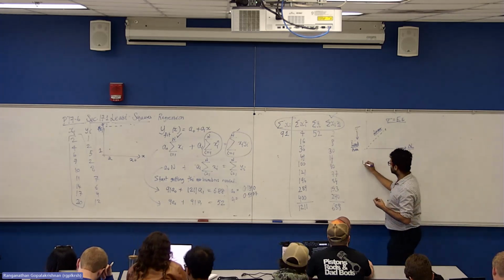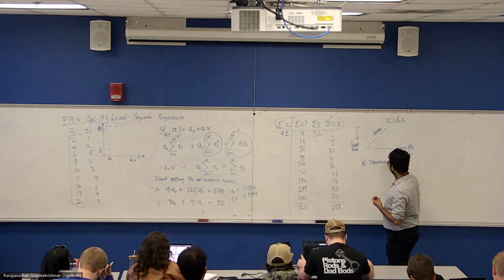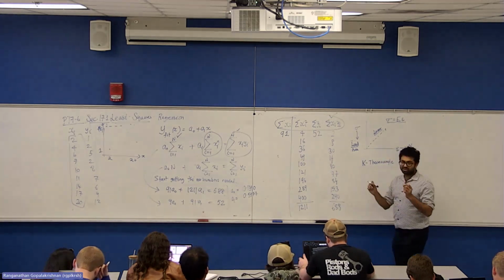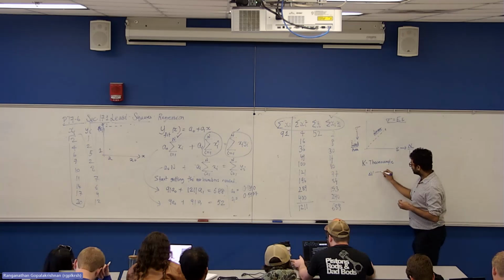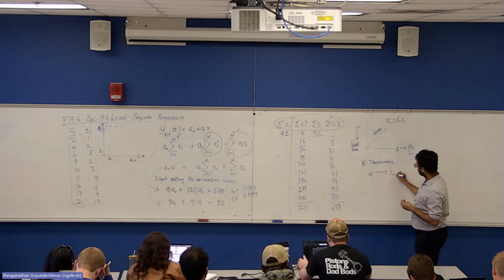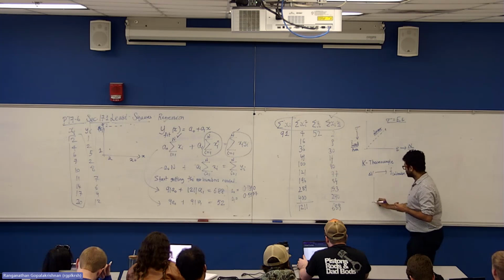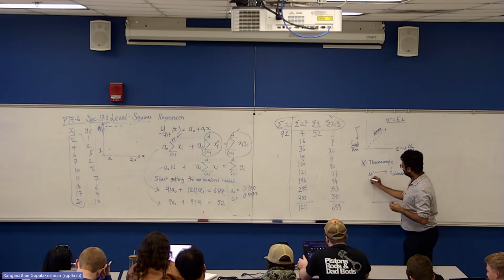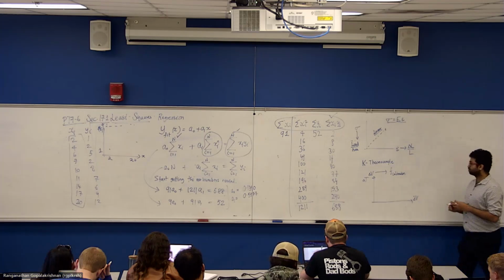So if you take, let's say, for example, a K-type thermocouple, what do you measure? You sense a voltage difference. Okay, that voltage difference goes into a calibration function. So calibration is essentially a relationship between the temperature difference and the voltage difference.